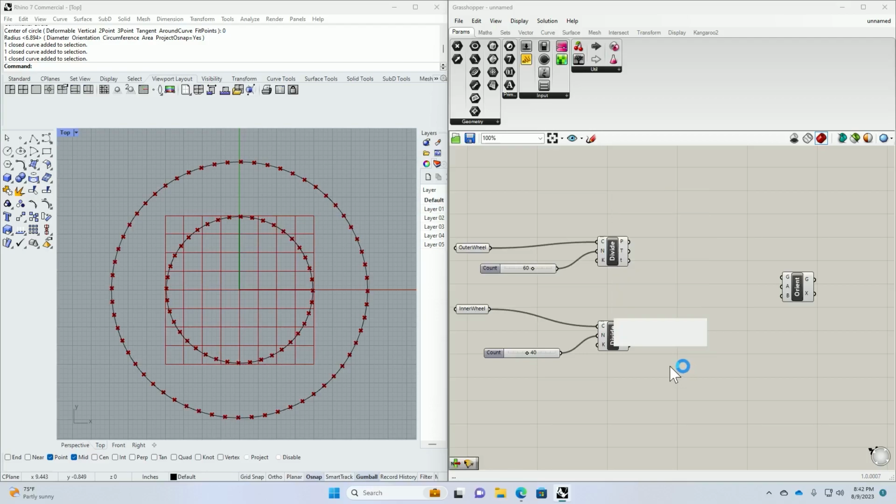Well, that's not what I need. I need the rotate vector. So what we're going to do is take this tangent vector, and rotate it 90 degrees, or 0.5 pi, around the z-axis, which in this view is coming out of the screen. It's handy because we're working in 2 dimensions. Sometimes figuring out an axis for a vector rotation can be tricky, but in this case it's really simple. So now if we call this the x vector and this the y vector, and this is the origin, we now have everything we need in order to construct a plane.